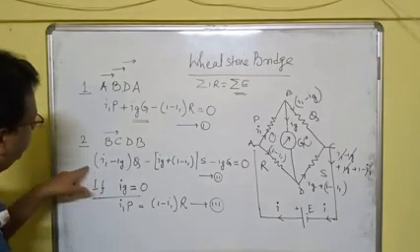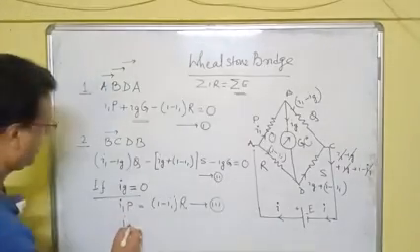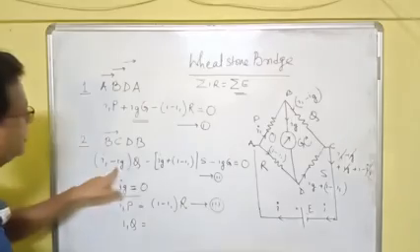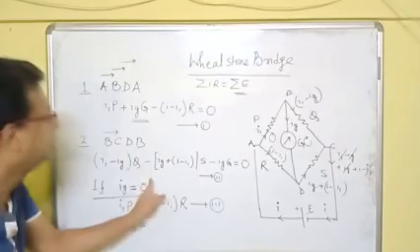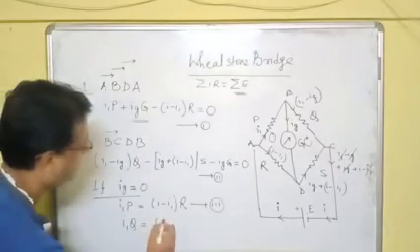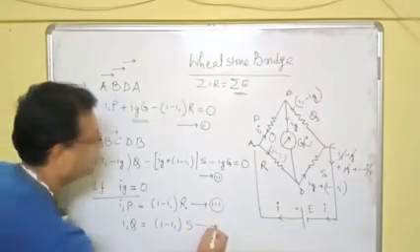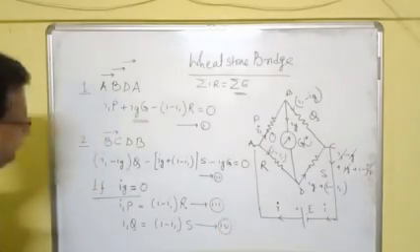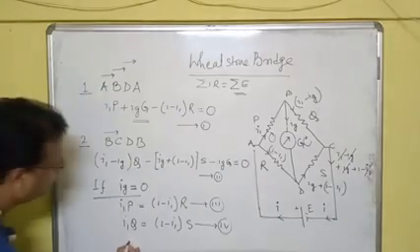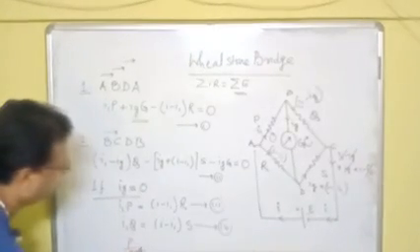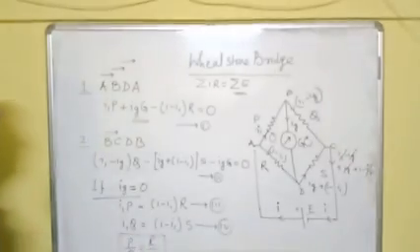And from here, if Ig is equal to 0, we get I1 Q is equal to, this part is 0, this is 0 again, so let us shift to this side, (I minus I1) into S. So this is equation number 4. Now if we divide equation 3 by 4, we get P by Q is equal to R by S.